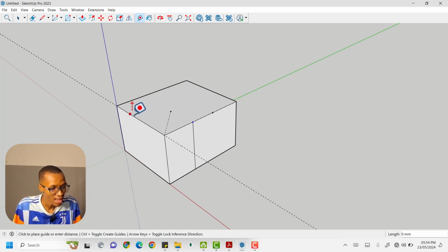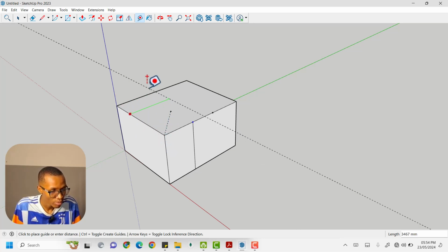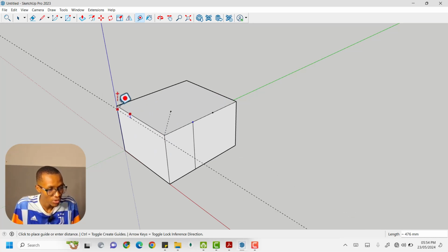That's an edge or a line guideline. The other one is a vertex guideline or point guideline, but this one is a line guideline. It draws a line using the axis, the direction of the edge in question. So I could pull that down, pull it up, pull it to the side, but it locks it onto that plane.